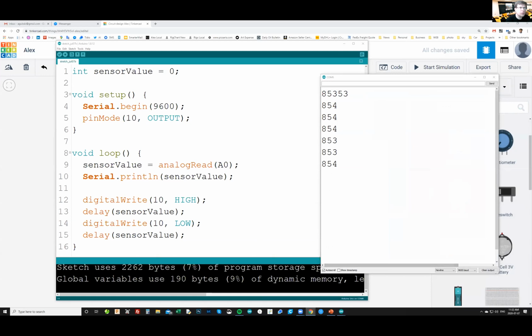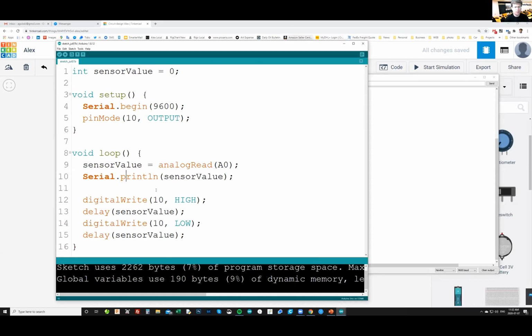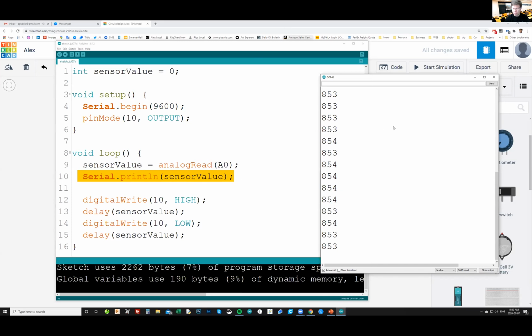There's another window here, but there's nothing in it. I plugged it in and everything, but when I turn the thing, the serial thing is not working. So when you press it, it doesn't show anything? Did you update your code with these two lines, serial begin and serial print? No. You need to update it because that's what makes it possible. This line, serial begin, and this line, serial print, print that sensor value onto the serial monitor on the computer, so you can troubleshoot what your potentiometer shows. Okay. So what am I supposed to do exactly? Because it still isn't blinking.